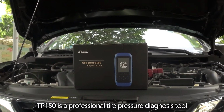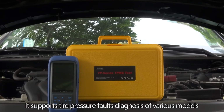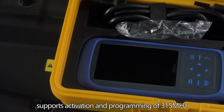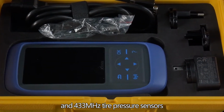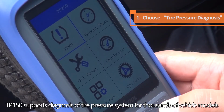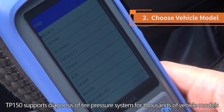TP150 is a professional tire pressure diagnosis tool. It supports diagnosis of tire pressure faults for various models, supports activation and programming of 315 MHz and 433 MHz tire pressure sensors, and reads live tire pressure data. TP150 supports diagnosis of the tire pressure system for thousands of vehicle models.